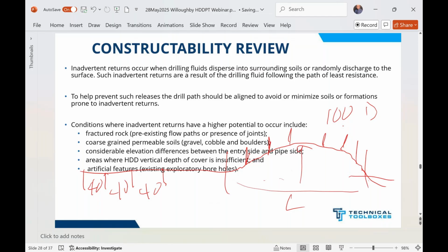So all that's based on not overstressing that pipe, being able to pick it up and get it down the hole. The higher he has to pick this up, that's why that catenary is so important. We never tell a contractor what his pick plan is. He does that. But I do want to know, my angle right here has a big impact on that pick plan, because the steeper that angle, the higher he's got to pick it up. And once he has to pick it up more than, say, 12, 15 feet, then he has to start using cranes and things of that nature, and they get a lot more expensive because it really increases the cost of your drill.